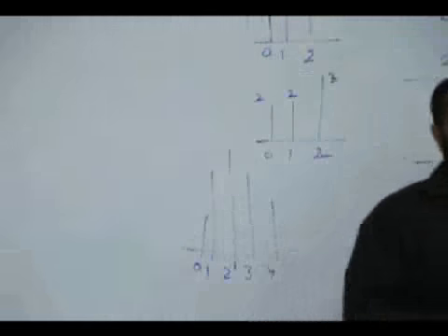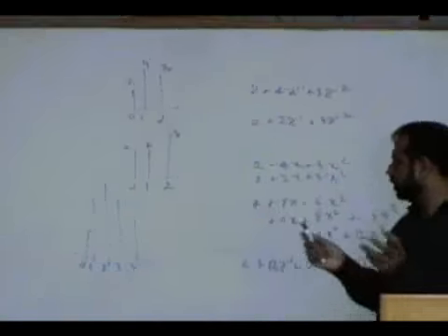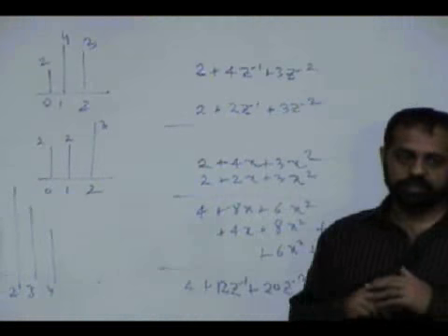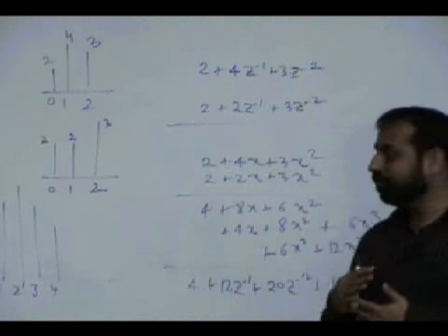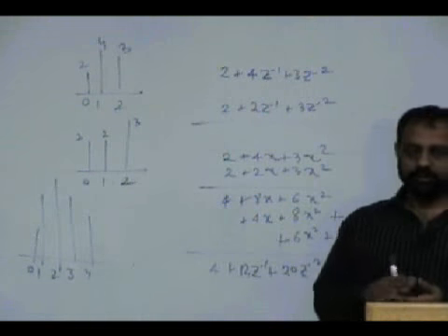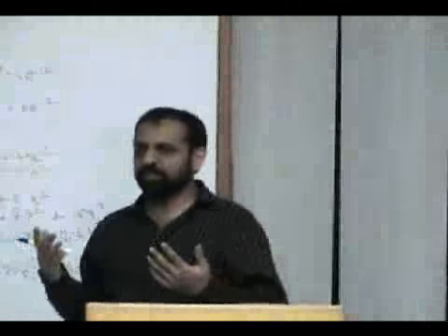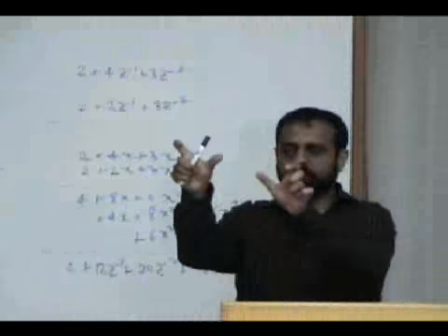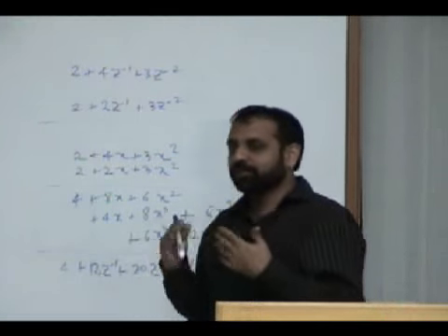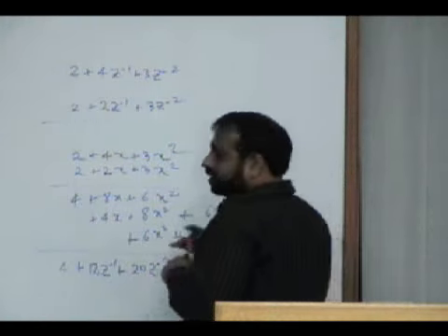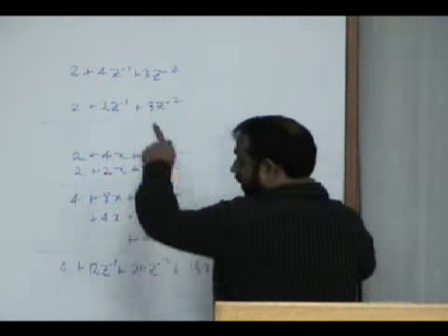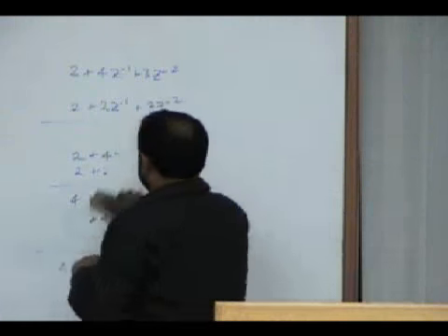So this is another way of performing convolution: you simply multiply the two polynomials together, and you get the answer of the convolution. In fact, whenever you are multiplying two polynomials together, you can use the MATLAB function conv to do that. If you have two polynomials you want to multiply together, just use convolve, write the coefficients of 1, coefficients of 2, and it will multiply the two polynomials together. Convolution is in fact multiplication of polynomials, right? Because of this property of Z transform, you take Z transform of 1, take Z transform of 2, what you get is the polynomial, and then multiplying them together means you're convolving in the time domain.